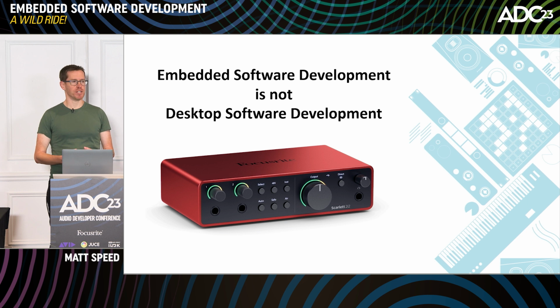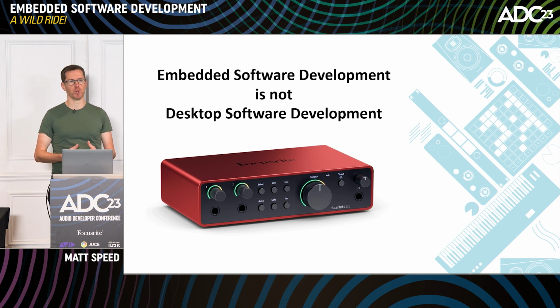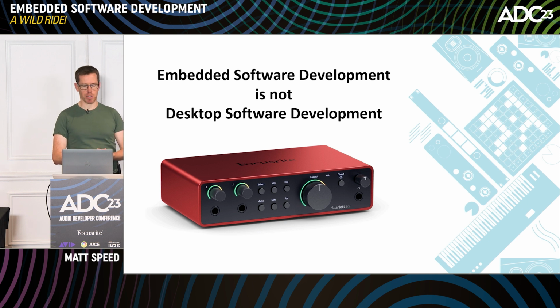We use firmware to abstract away all of the aspects of the processor that you need to bring it up from this being a useless pile of transistors into something that can be used from high-level software. So we define a hardware abstraction layer. Looks a lot like an API, and this defines how software can access file systems or USB or MIDI or all the stuff that's processor specific and you need to care about the implementation.